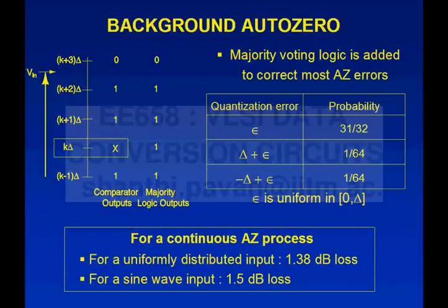Typically what happens is that you will design a 6-bit flash, but you get a lower effective number of bits after you build it because of DNL and all that, and the quantization noise will go up. There will also be distortion because of the track and hold not being as ideal as you would want. Bearing all this in mind, a practical converter that gets 5 or 5.2 effective number of bits is actually doing pretty well.